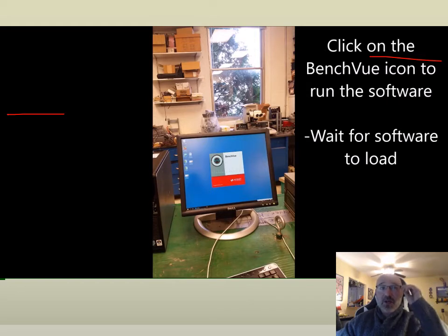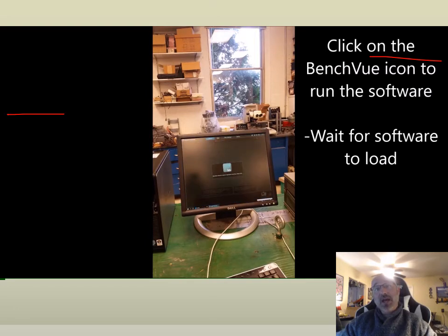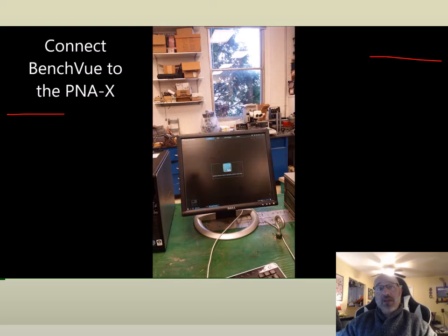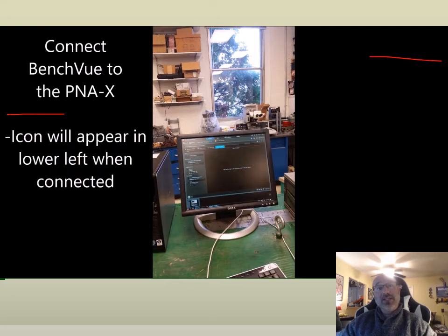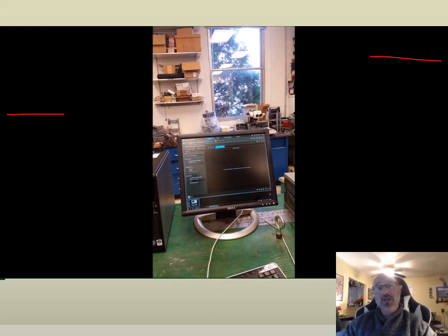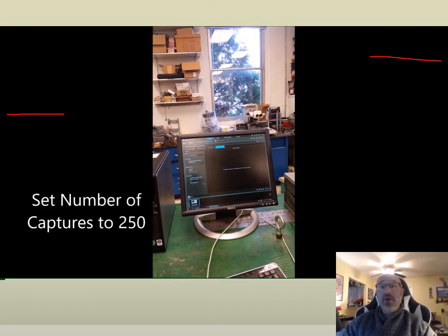So this over here that we're looking at now is our BenchView software, and BenchView is our data acquisition software. When the radar antennas on our linear drive receive the reflected data, it comes back and saves it on this program over here, where it timestamps it and position stamps it with the information from our sensors within our system on the linear drive.